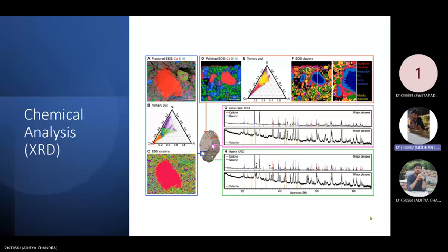The chemical analysis method is also a very accurate and prompt method to gain insights. Coming to the chemical analysis, we have the XRD method. What does XRD stand for? It is X-ray diffraction. The X-rays emitted by these samples undergo diffraction, and we are able to capture it in the form of graphs, which give us further insights about the Roman concrete, like defining the compositions of calcite and quartz, which play a key role in the self-healing property and the curing property of the Roman concrete.